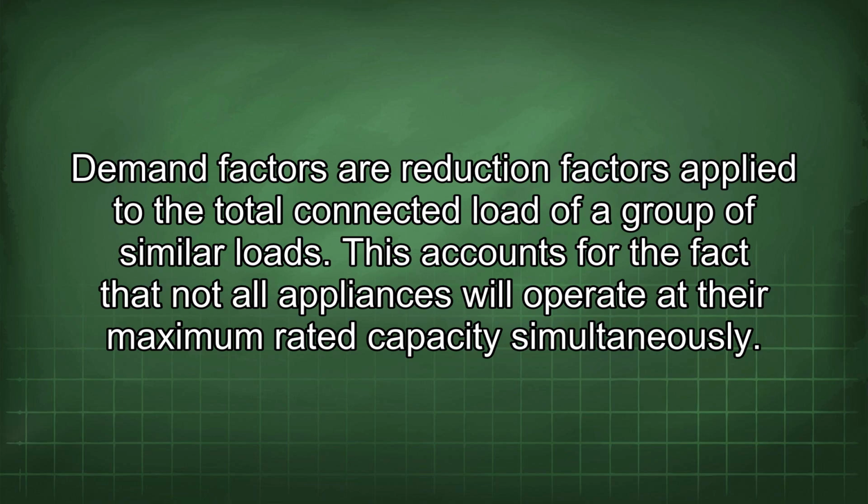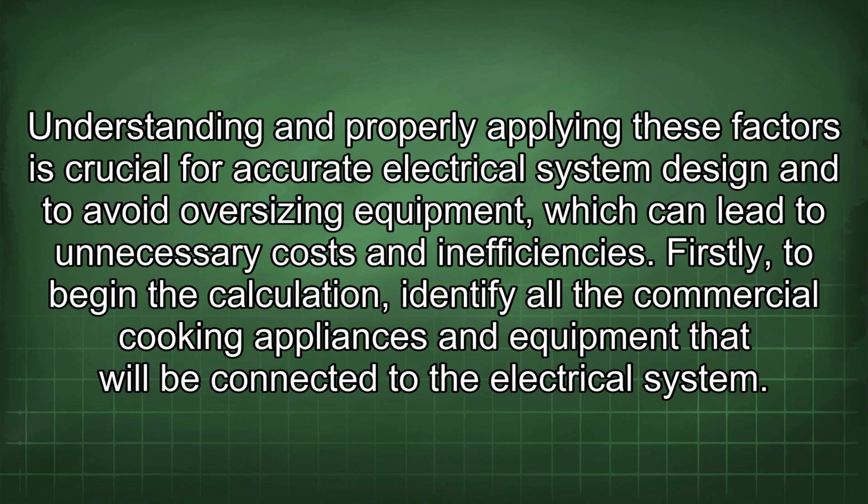Demand factors are reduction factors applied to the total connected load of a group of similar loads. This accounts for the fact that not all appliances will operate at their maximum rated capacity simultaneously. Understanding and properly applying these factors is crucial for accurate electrical system design and to avoid oversizing equipment, which can lead to unnecessary costs and inefficiencies.